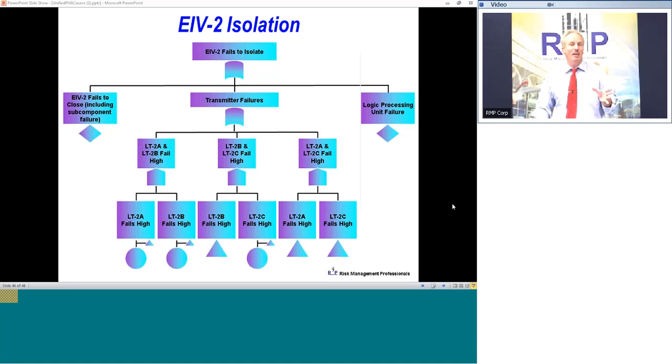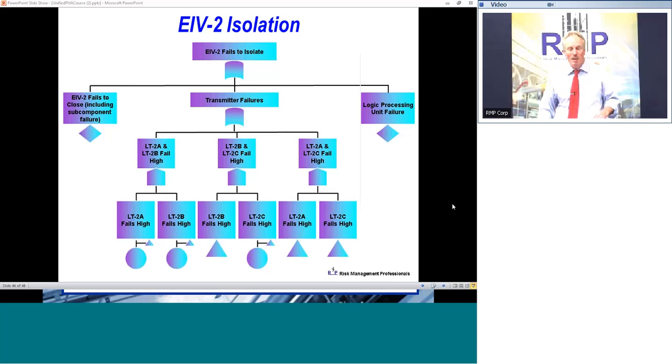So again, these things can get flushed out if you understand the scenario. In this particular case, understand the consequences. How does it correlate with your risk threshold? And having this laid out as a scenario, maybe through the use of a HAZOP during the design process, selective application of LOPA can help make critical decisions that help the designer get the job done without overdoing it or without missing critical safety weaknesses. So, a couple of examples on how you might use risk-based decision making.